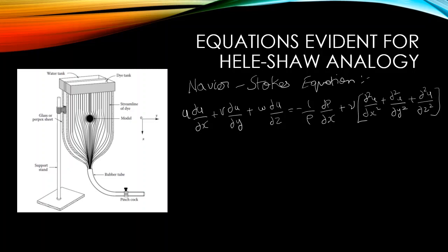I'm going to write the second equation, the y momentum equation. So dou v by dou x. It's very simple. When you write the Navier-Stokes equation for the x equation, we can simply change the velocity alone, right? I'm just going to change the x velocity component u to the y velocity component v.